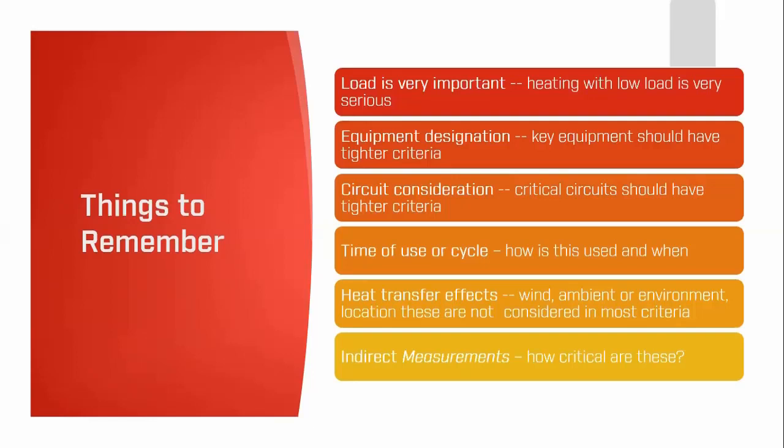ways. Indirect measurements. This is where the source of the heat is situated behind another surface. We know the camera is not an X-ray machine, and the camera only measures the surface it can see. The image relates to the effect on that component from its internal source of energy, and we interpret the patterns. So anomalies found from indirect imaging can be misstated as the understanding of the severity or the extent that the internal problem is overlooked. And this is where the skill of the thermographer with the knowledge of the application is paramount. Understanding implications and the application of severity criteria is not to be underestimated.